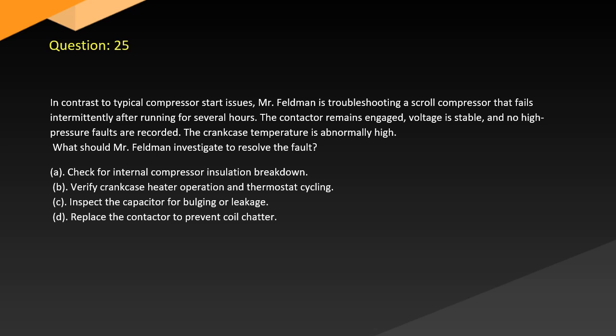Question 25. In contrast to typical compressor start issues, Feldman is troubleshooting a scroll compressor that fails intermittently after running for several hours. The contactor remains engaged, voltage is stable, and no high-pressure faults are recorded. The crankcase temperature is abnormally high. What should Feldman investigate to resolve the fault?